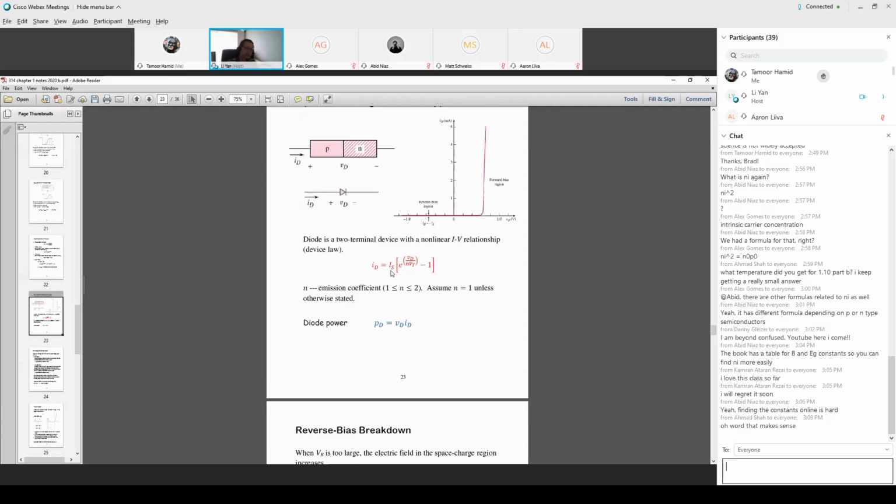In a device, we call that a dark current. Did that answer your question? Yes, thank you. It is the maximum under reverse bias, but nonetheless very tiny. Normally you talk about microamps, milliamps or amps, so you basically ignore it. Sometimes even if you don't ignore it, you call it a dark current.